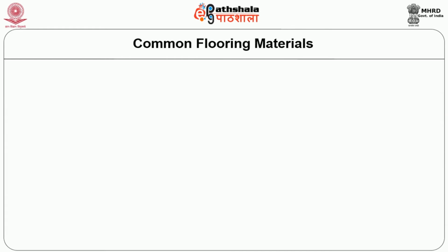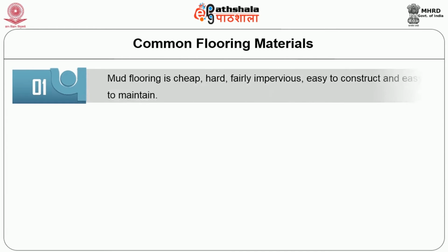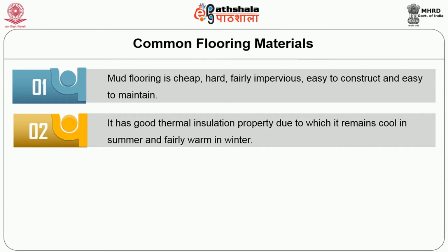The common flooring material that is available now is mud flooring, and mud flooring is actually cheap, hard, fairly impervious, easy to construct and easy to maintain. It has got good thermal insulation property and is fairly warm in the winter.